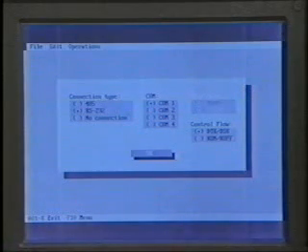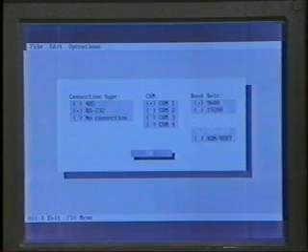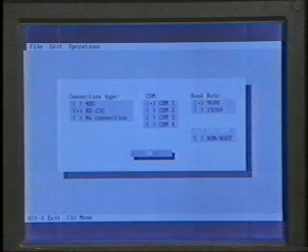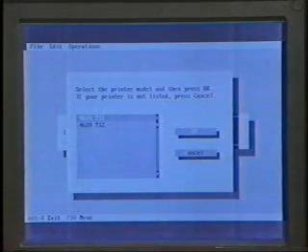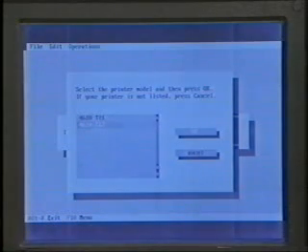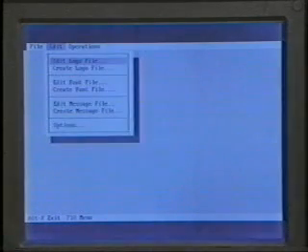At baud rate, select 9600 or whatever rate your printer is set for. At control flow, select DTR/DSR and press Enter. At printer model, select 4610 TI-2 and press Enter. At this screen, press F10, then the right arrow. This will take you to the Edit window.